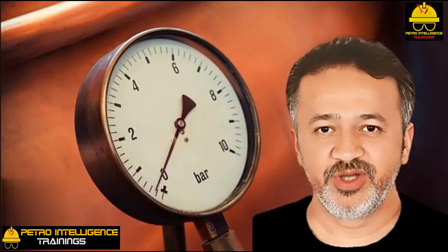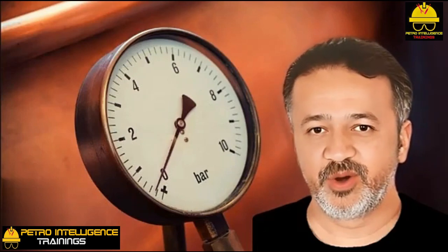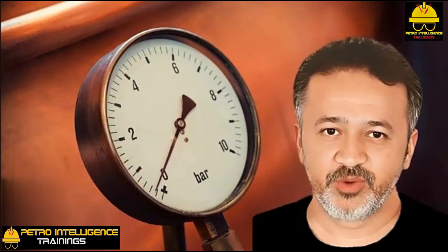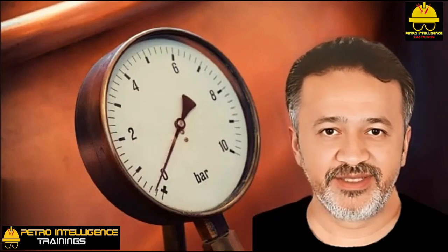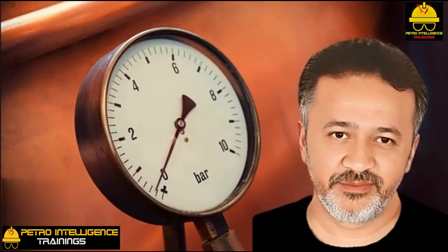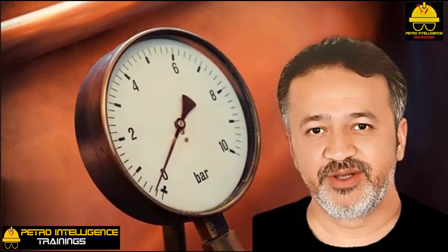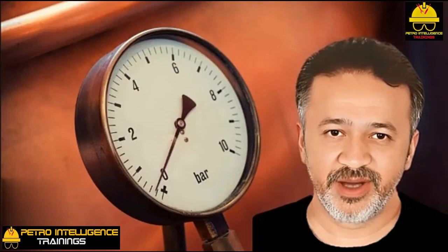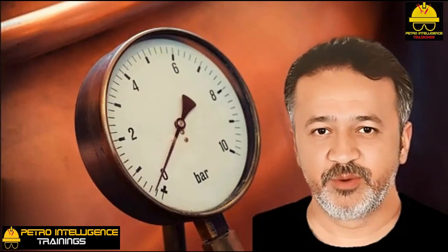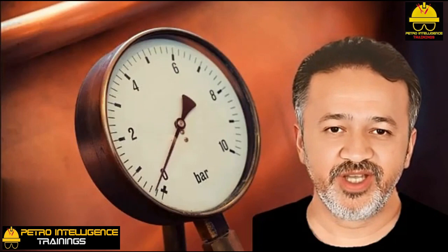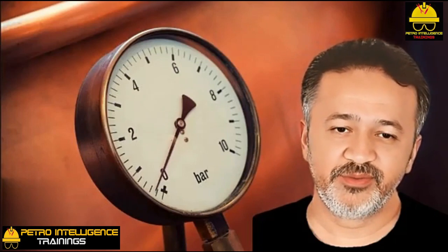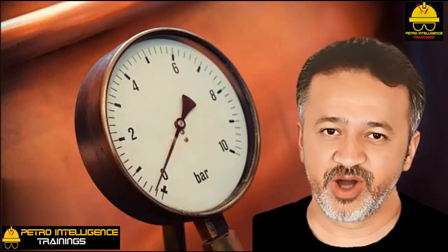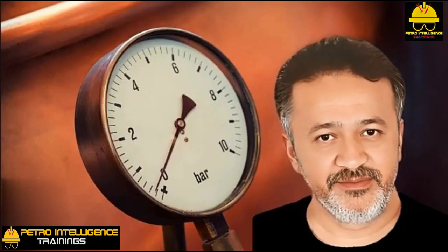X-ray level detection works with a source of radiation and a receiver, located on either side of the vessel. As the percent absorption of the radiation increases, the receiver sees fewer X-rays and a higher density is implied. The X-rays are absorbed by steel components, such as ladders and manways, which can sometimes be confusing. Either method discriminates nicely between clear liquid, foam, or vapor. Such a level controller can be calibrated to hold a foam level or a liquid level. Of course, this sort of level detection is far more expensive than conventional techniques.